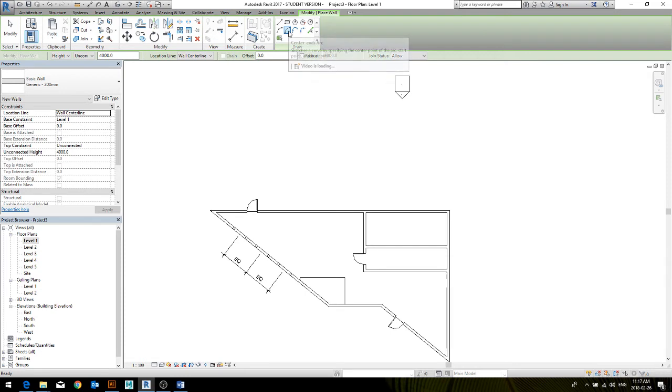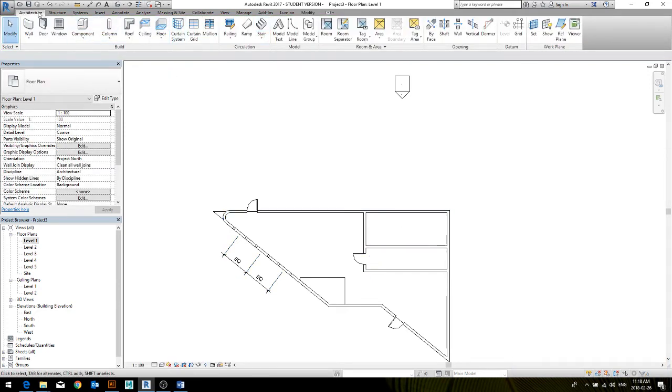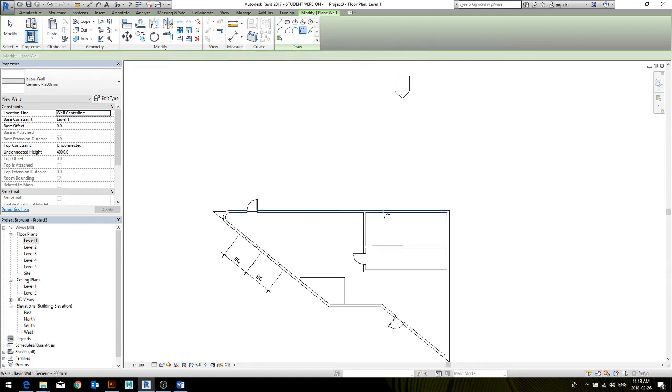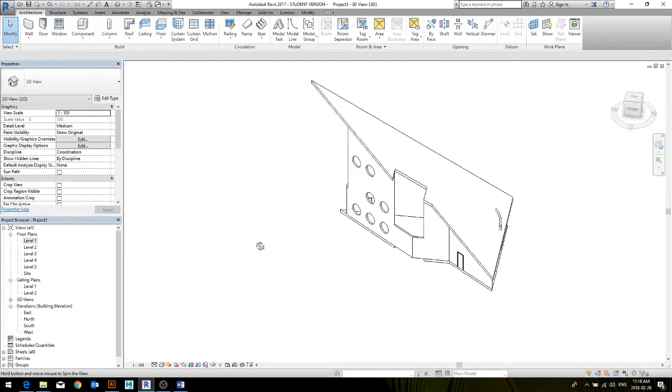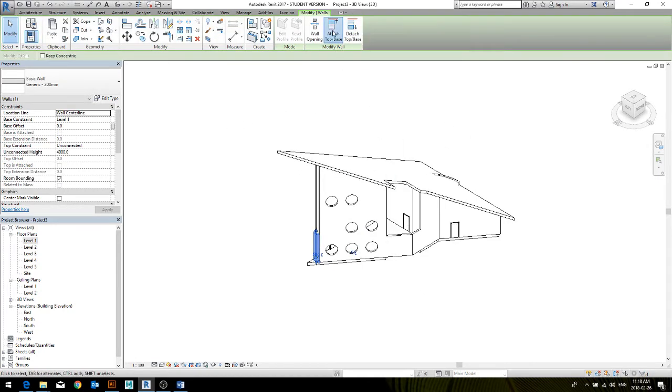In one of the tutorials in the future, I'm going to cover the whole massing thing in Revit. A part of that is that whatever you have in your Rhino model as NURBS or polys, you can bring into Revit and define them as walls and floors and use what you have modeled outside. But there are also tools in Revit that let you do massing in more complicated curvature or angular forms that are not very easily achieved with walls. There are some approaches to them, and you can still draw curves and some softness could be defined this way, but there are better ways for doing this that I'm going to show you later.